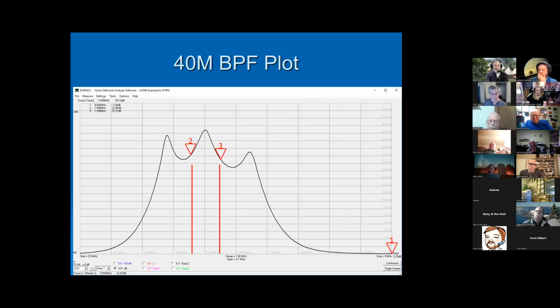So here's an interesting one. And the reason I'm giving this is really to give you a picture, that these bandpass filters are not like that first 40-meter one. That's an exception, huge exception. The stuff I'm going to show you now is more of reality. So you have to understand that these guys aren't perfect as far as how they attenuate signals, how much attenuation, the skirts that you have on it, and the efficiency losses that you have with these things are not real good.